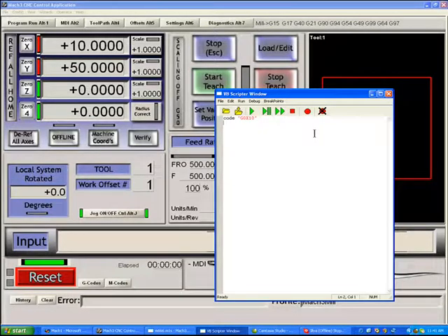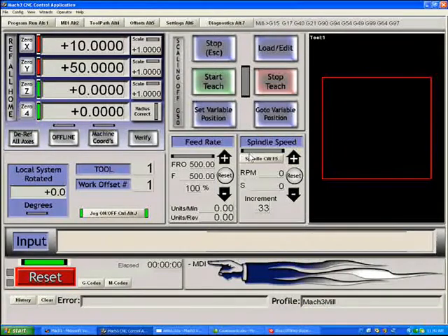Play with the commands, play with other people's scripts, get used to the Visual Basic Scripter. If you want to do complex Modbus operations and complex script operations, you'll need to become proficient at it. For those of you who don't intend to do anything other than run G-code, you really didn't need to watch this video, because the Visual Basic scripts which are added into the program are sufficient to do most jobs for most users. So that's it for an introduction to Visual Basic scripting.